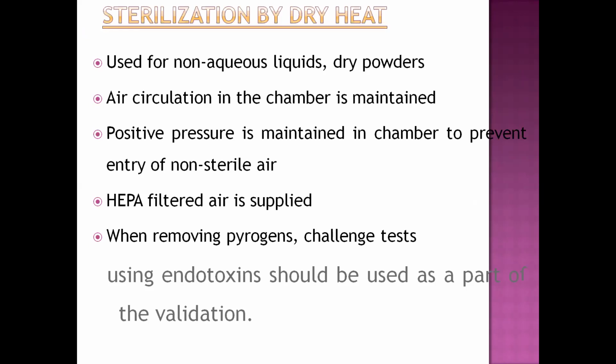Positive pressure should be maintained to prevent the entry of non-sterile air. Then HEPA filters: HEPA filtered air is supplied, and for removing pyrogens, challenge tests using endotoxin should be used as an evaluation.